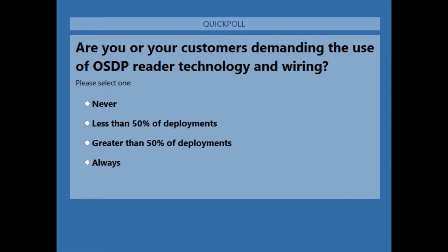Now, if you're going to use just one reader per reader port, one OSDP per reader port, which is what we suggest, then you don't need to change anything, either for HID, Allegion, or any other. You should be fine, because by default they all come in with address 0, which is the same address that ACM will read just fine. Okay, so keep that in mind.